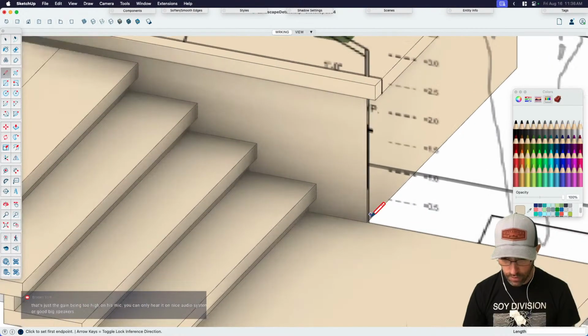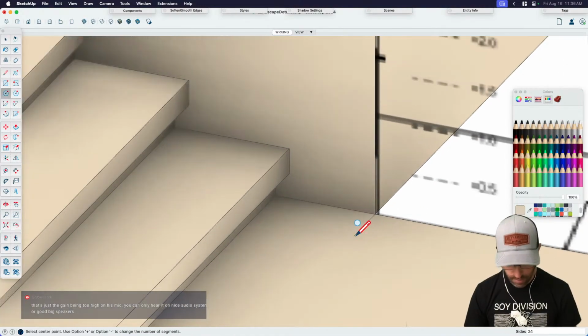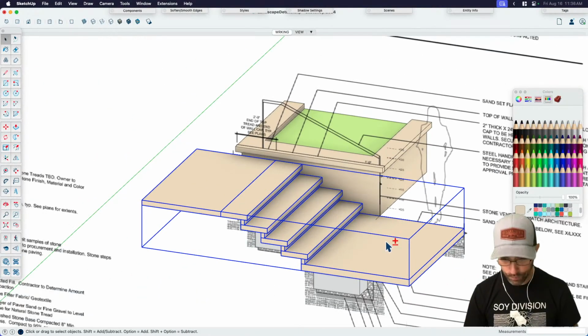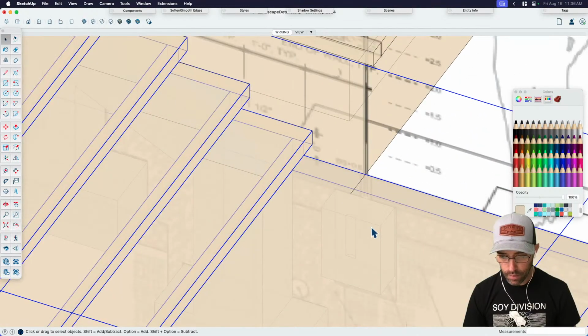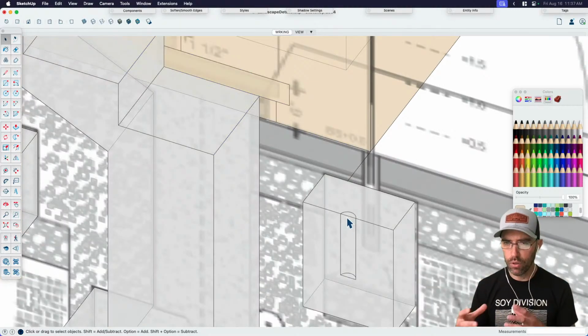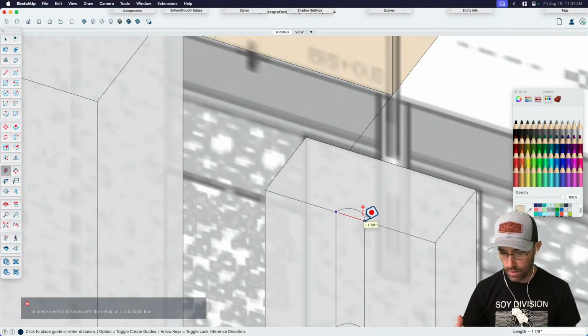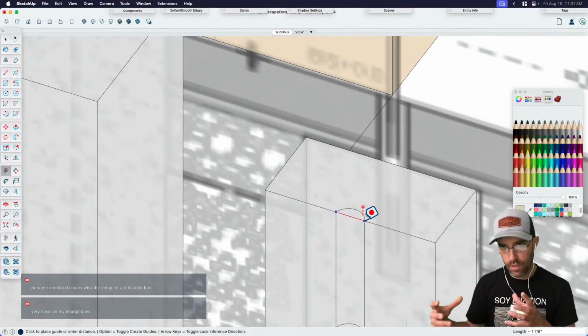So let's do this. Let's bring this handrail 6 inches off, and then this is where I've got to think for a second. I already know that I punched a hole in this footing. You can see this footing below here. I want to make sure that not only am I drawing my handrail centered on this hole, but that I'm using the same distance.